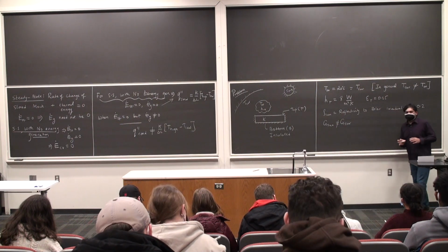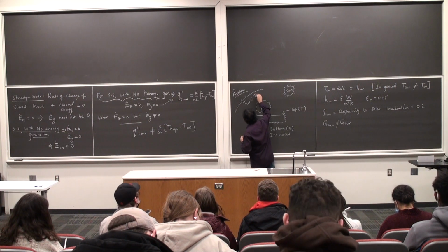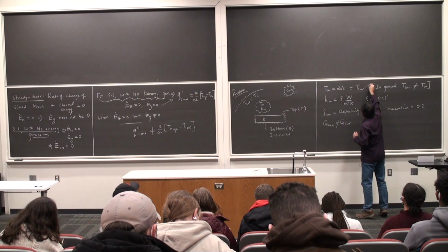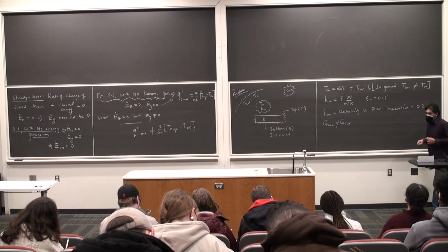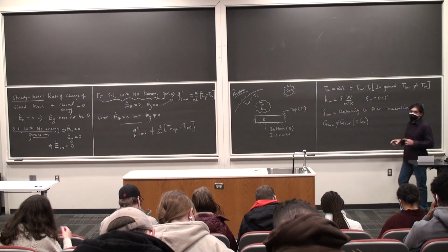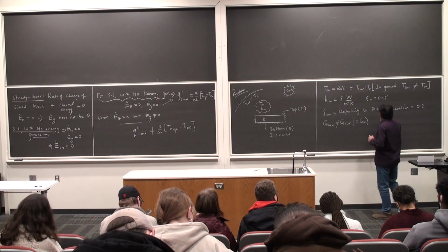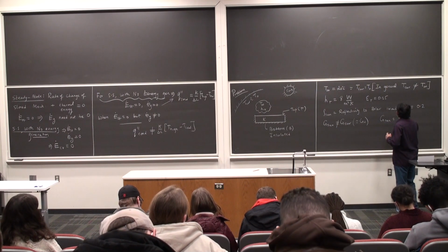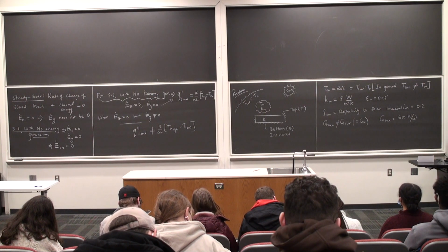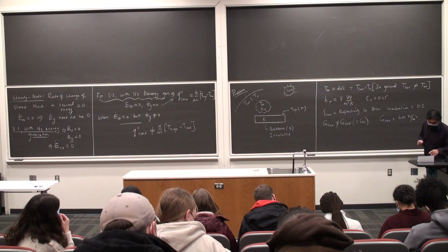This is not G surrounding, and I'm going to write the surrounding with a subscript O so that I don't confuse SUR and SUN. So G surrounding is G naught. G sun is different from G surrounding. And you are told that G sun is 600 watts per meter square. So this is a flux, which means that it has to have units of watts per meter square. And you are also told some additional information.